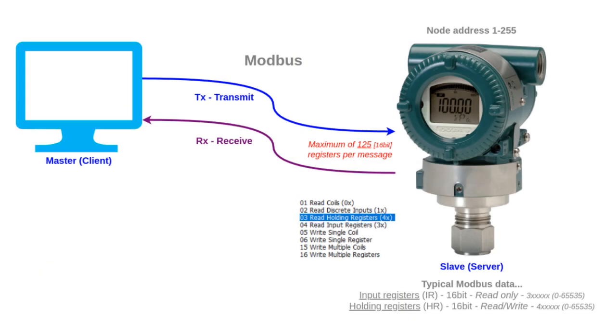The protocol uses a Modbus master and a Modbus slave. A Modbus master will request data from a slave device. When using Modbus TCP, a Modbus master is known as a client, and a Modbus slave is known as a server. In a real application, a pressure or temperature transmitter shall typically be a Modbus slave or server. This contains useful data we want to access. A Modbus master may typically be a PLC or computer which needs to read data from remote devices or equipment. A Modbus slave will only communicate in response to a message from the Modbus master.